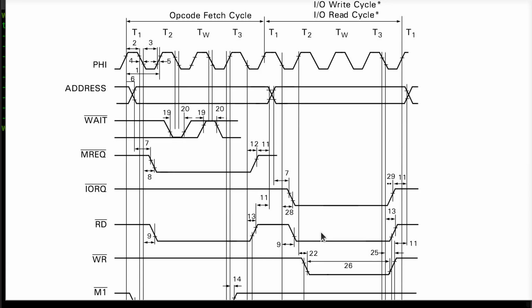As it consumes data from the CPU, it may do this over and over again, accepting one byte per transfer and storing it in a set of registers, which is what you have in Z80 peripherals all the time. You have the OUT-IR, or the OTIR instruction, which is a repeated output instruction that continuously writes bytes to the same I/O port address. That's why you need one and only one edge so that you can advance your counter.